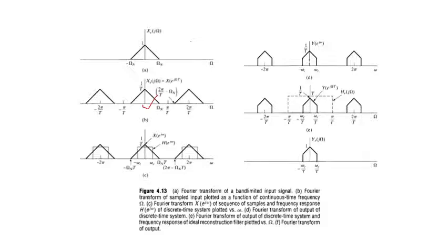So it is known that this small omega c is less than this omega N. One more important thing is that we need to apply the filter. This filter is in discrete, so we have to convert this into discrete. So how can we convert this upper graph into discrete? By simply multiplying it by T.